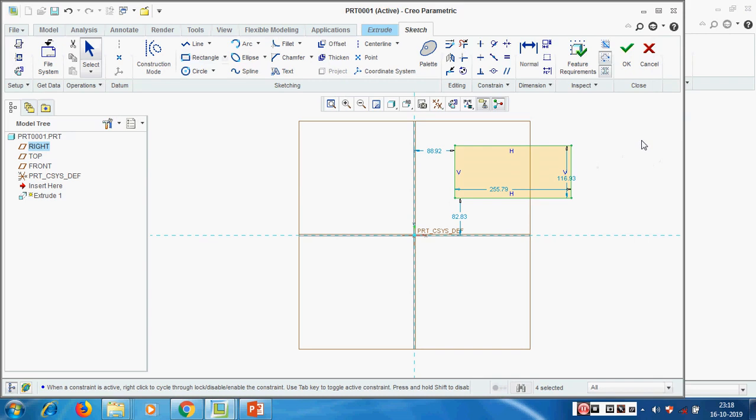Pick the middle button, create the dimension. In the initial stage, please create some dimensions. Later, we can modify the existing weak dimensions. Pick one. Just pick the entity and middle button. This, then the reference dimension. From here to here, just pick two entities and pick the middle one. Similarly, pick this entity and pick this reference.